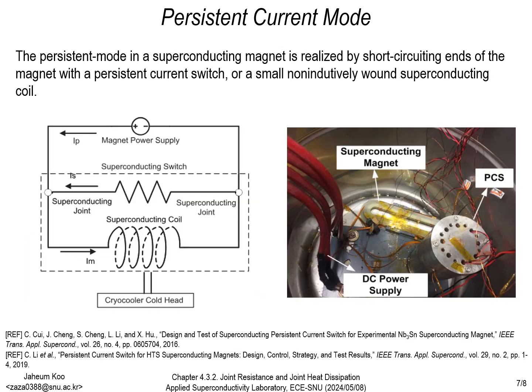Currently, MRI machines utilize shorted superconducting loops to implement a persistent current mode. First, a heater is activated within the system to temporarily disable the shorted superconducting loop. Next, the magnet is charged by supplying current from a power supply. This current energizes the magnet to the required field strength.